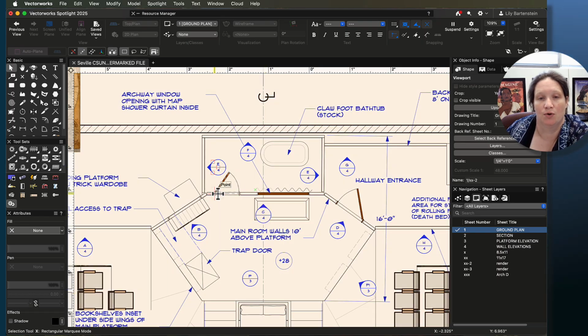If I'm looking for this wall, which has a door in it and a window in it, I'm going to also look on sheet 4 for that, but I'm going to go look for drawing C. Or if I'm looking for the P, the platform, this is its drawing label P over 3, so it's living on sheet 3, and the detailed information about it will be there.